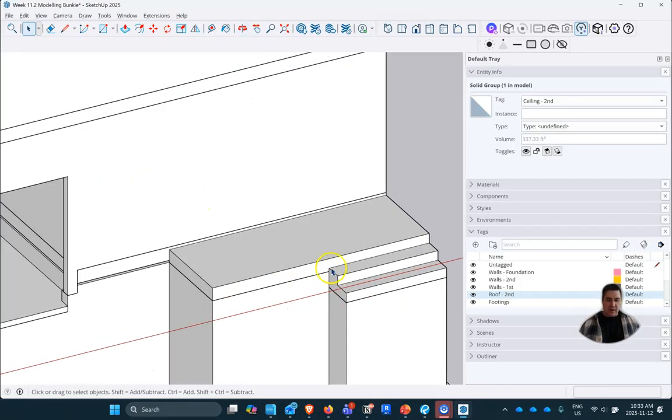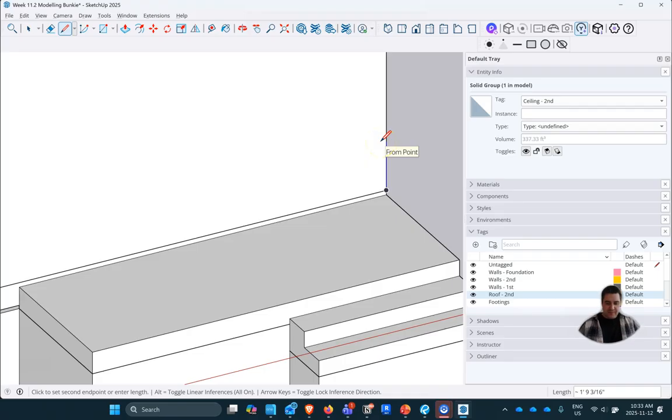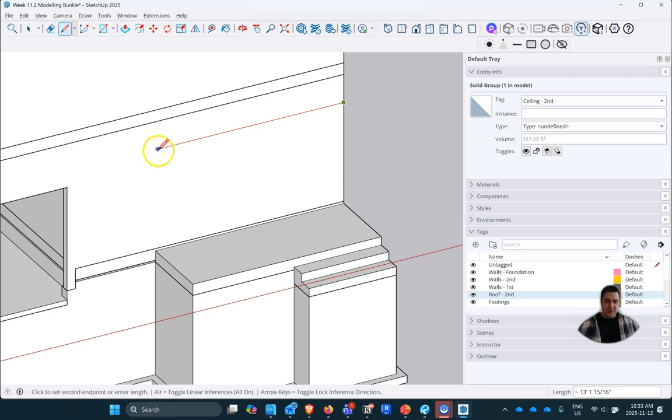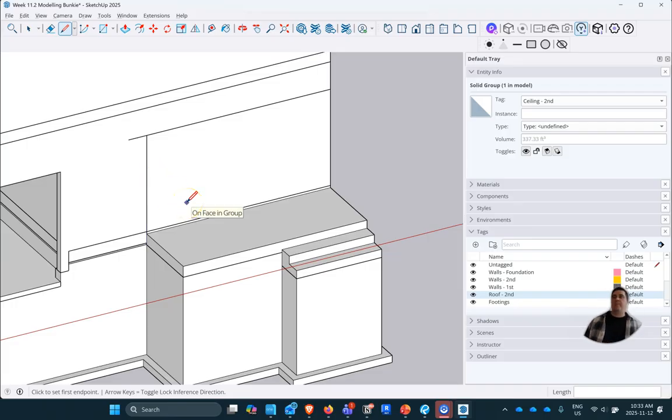And with this, we're going to go from our subfloor. Our subfloor is this top line here. We're going to go up 7 feet. And we have a line here. And I'm just going to draw this line across like this. And I don't need to necessarily go to the top line. I'm just going to model that line up like that. And so that's kind of the bottom of our beams. And actually, that's the top of our door, not the bottom of our beam. So that's our 7 feet. And so realistically, let's kind of mock up the rest of this area here.